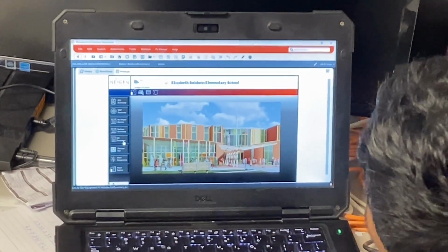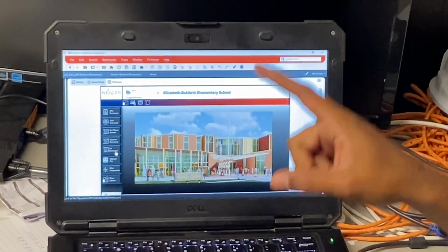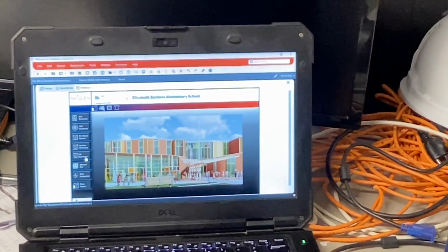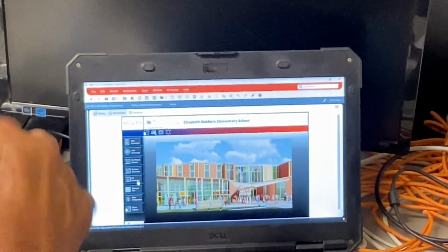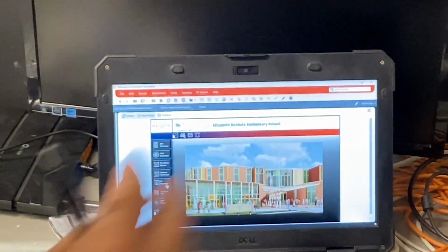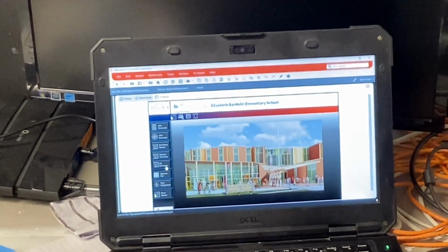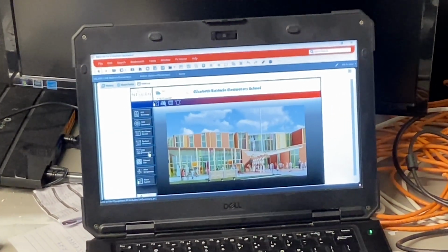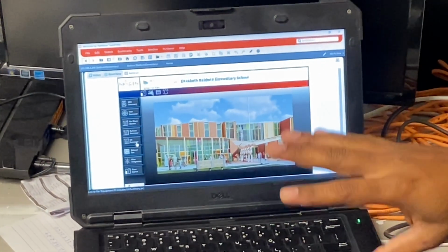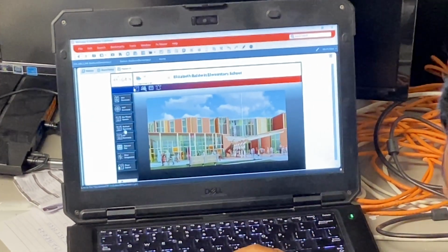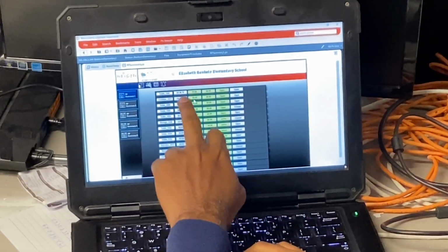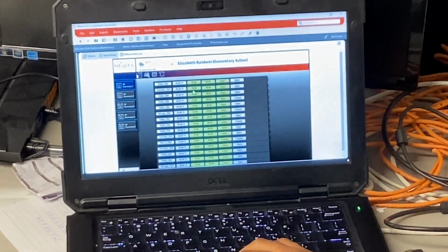And what about the radiant panels in the hallways, stairwells, whatever? Is that part of the schedule? If we have a schedule for the whole building, does it turn those to night setback also, or do those keep running? They have the schedule as well. They have an occupied set point and a non-occupied set point. Okay, that was my question.